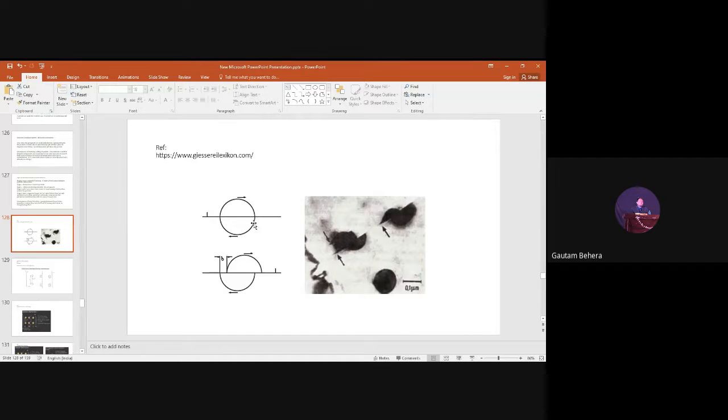This is the image before cutting. The dislocation is present over here. The dislocation is gliding and cutting the precipitate into two halves, right? So which is the image of this one? The precipitate is getting cut by the dislocation, and the dislocation is now free to move. It is gliding again, and it is here.